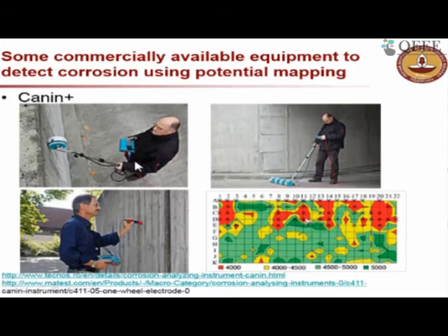And we looked at different ways of either coating the rebar, with metallic coating, or using a chemical in the concrete, so that we can increase the chloride threshold of the system, and by which we can then increase the service life. And then we also mentioned that moisture and oxygen are essential for corrosion to occur, and if chlorides and carbon dioxide are present, then the chances of corrosion are higher.